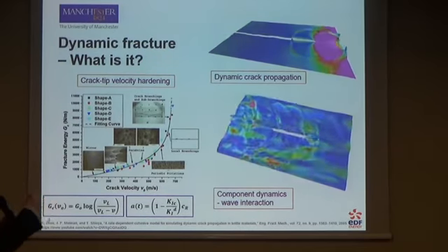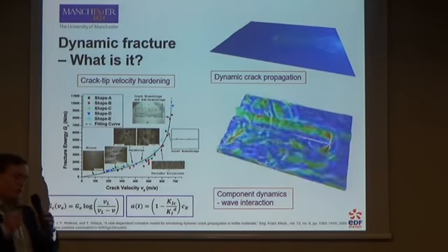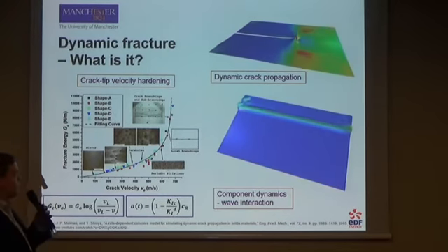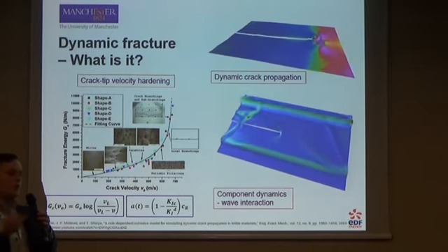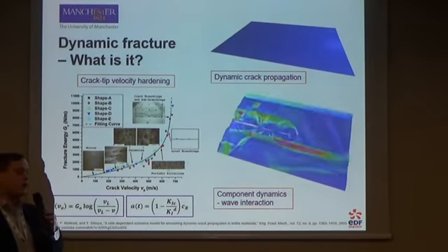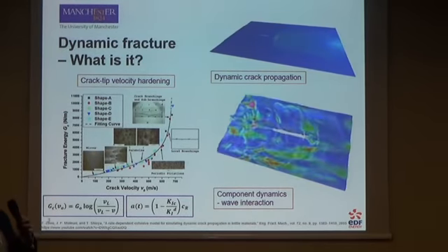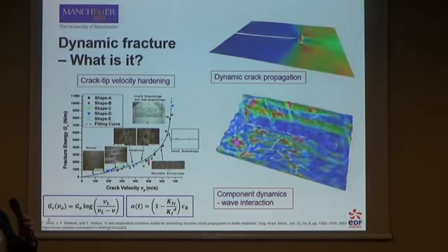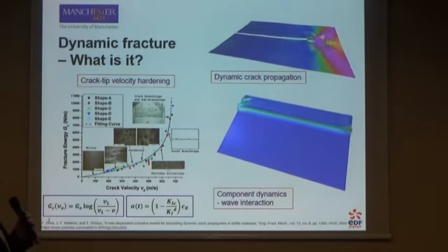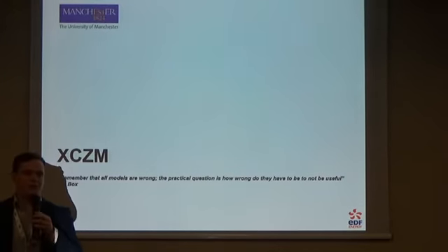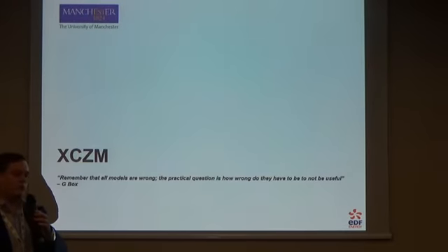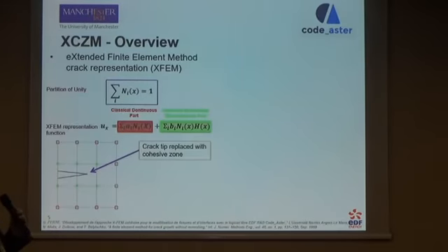In particular, you can notice we go from a region where the stress initiation is dominated by maximum stress, whereas in the propagation it's due to the bulk material properties. So we're looking for something that's able to cope with this phase transition, as it were, between something that's slow and something very quick. So from this, there's an approach that I'm considering called the extended finite element method with cohesive zones, as you may know as well.